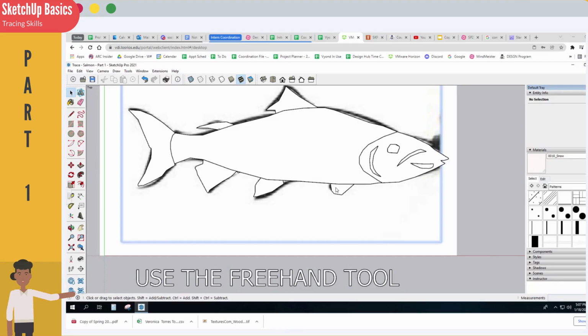The next special thing is to add texture. See the toolbar at the top and make sure the black and brown box is selected to show textures. Then select the Materials palette on the right. Choose the Pattern selections. And then scroll down to find Scales. Add them to the model. Then make a copy so that you can change their size. These ones are too big.